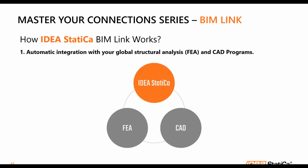So after the installation, the program automatically integrates BIM Link with the FEA programs and CAD programs that are already installed on your PC. And should you want to install your software after IDEA StatiCa has been installed, you can install it using the BIM Link installer. Later on, I will show you how to do it very briefly.